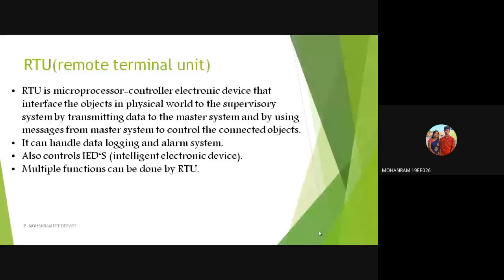Next, RTU. RTU is nothing but a remote terminal unit. It is a microprocessor controlled device, and it is also called a remote telemetry unit. It has more inputs and more outputs. Unlike PLC, it needs no programming. It is already customized by the user and has embedded features previously, and it is larger in size when compared to PLC.